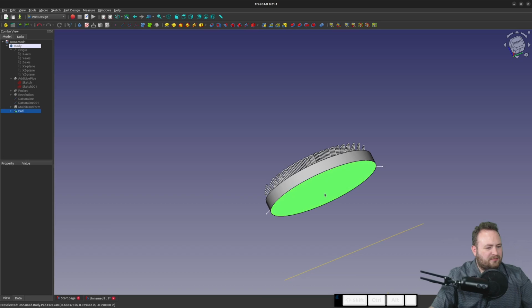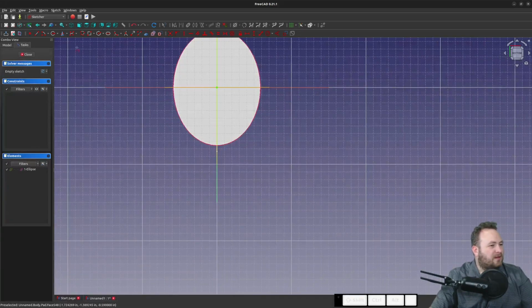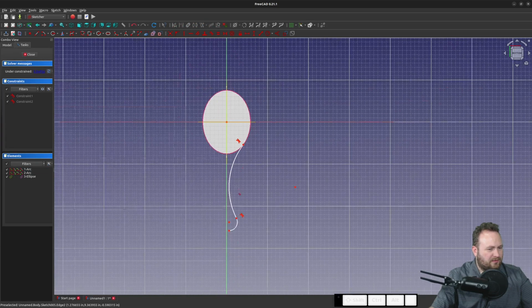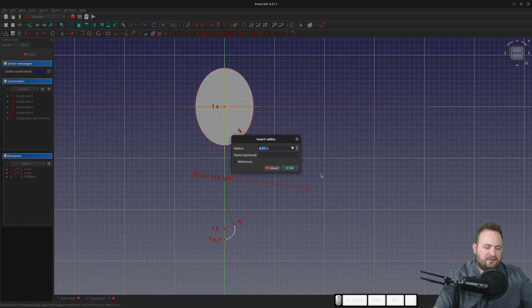Next, let's work on a handle, right? Sketch on the bottom face. And I'll add in my external reference there. So we've got, I think, yeah, that's a perfect ellipse, all right. And I can add in there, and I'll grab my tangent relation with T. Here and here. And I can start making some dimensions. I'll give a vertical here and here while I'm at it, and then here to the origin. So we can say something like radius of 7.08.